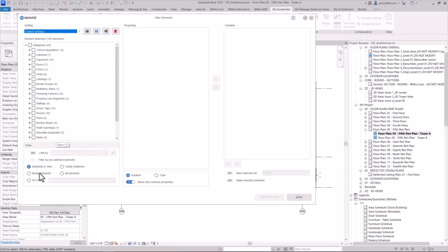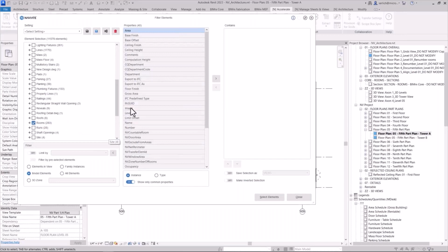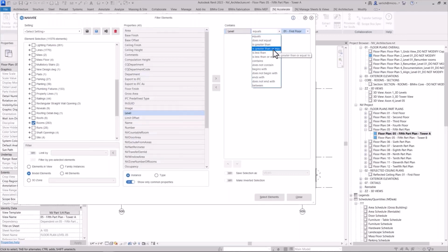And these Naviate filters are really easy to use because it's the same concept as using the Revit rule-based filters. Because the rule-based filters, what do you do? You select a category, select some parameters, and create your rule. Equals, contains, doesn't contain, greater than, you get it, because you've done it for the visibility and graphics. This is the same thing, but you're creating Naviate filters.